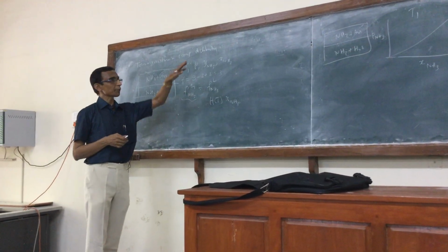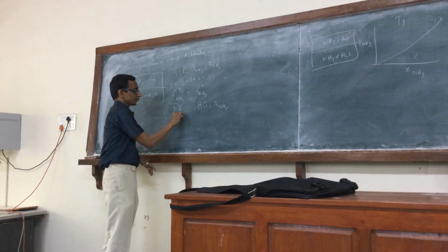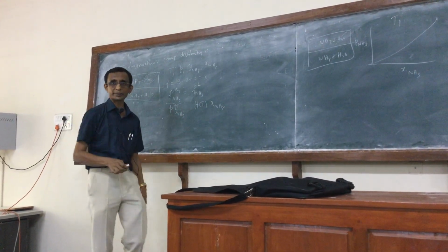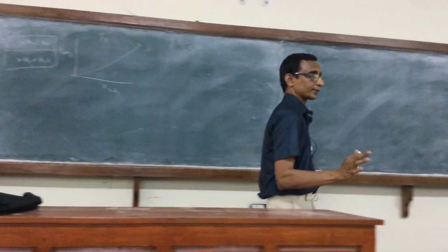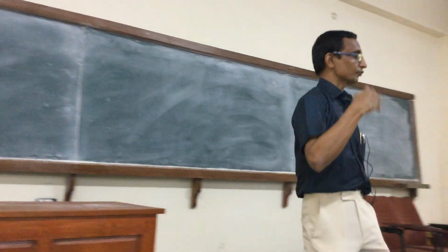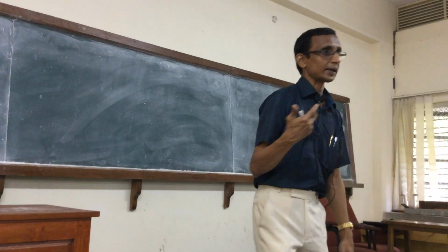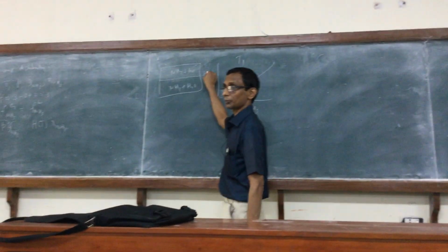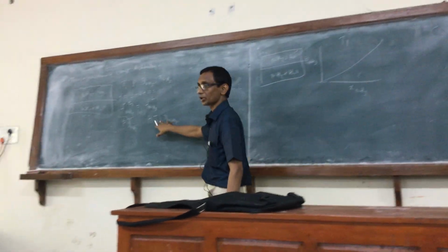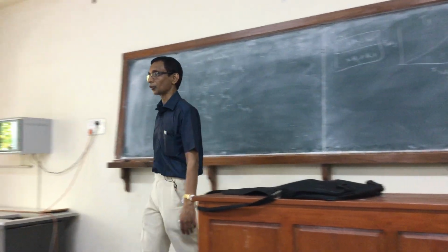So what Taylor says is correct, provided we now treat the gas as an ideal gas mixture. Under that assumption, what he is saying is correct, that the pressure axis for the pure component can in fact be treated as the partial pressure, because the right hand side hasn't changed. So whatever was the pressure earlier now becomes the partial pressure of ammonia. So we can use it.